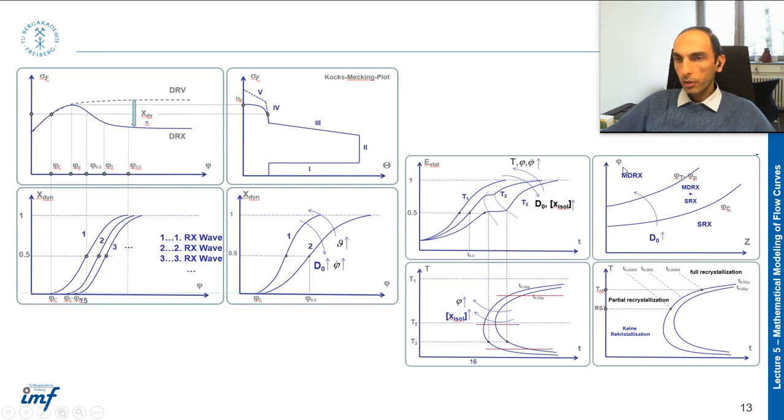Here you have metadynamic recrystallization, and if you increase the Zener-Hollomon parameter more, metadynamic recrystallization and static recrystallization together, and in this area just static recrystallization.